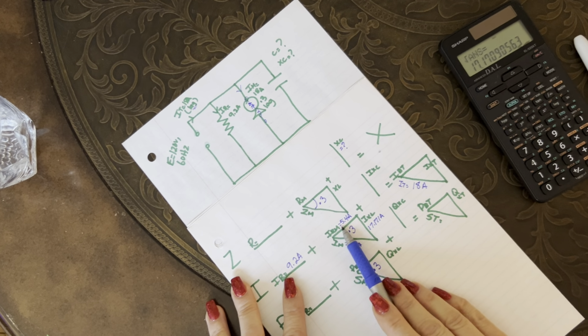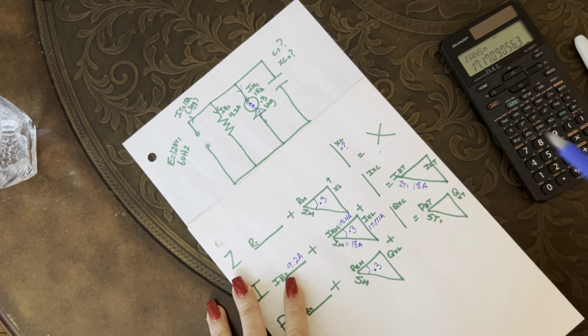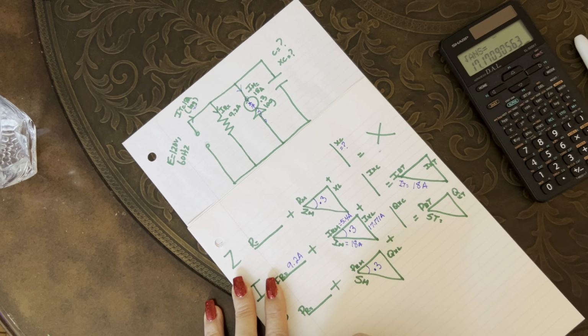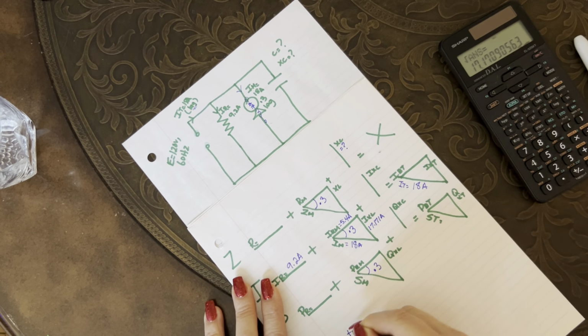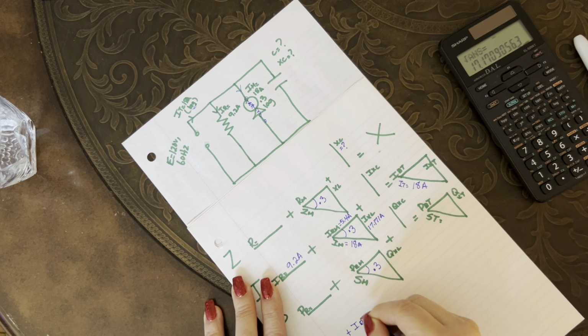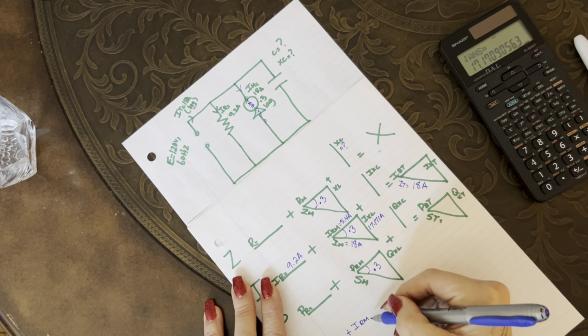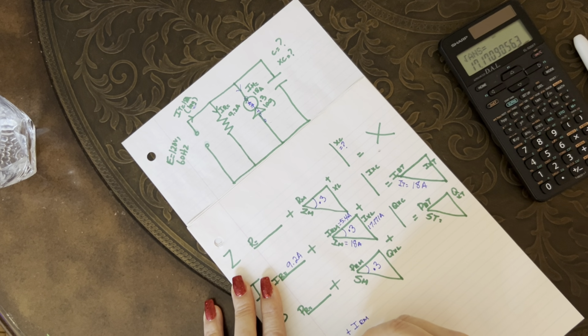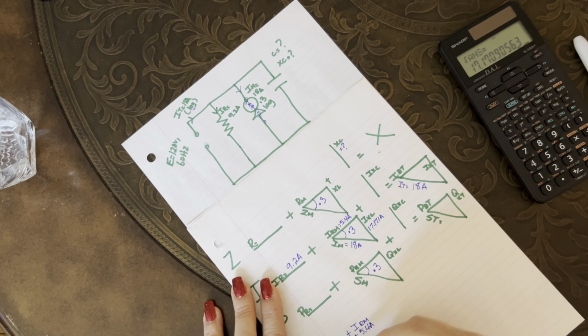So I can take those two values to populate my IR total for the circuit, right? So my IR total equals IR plus IR motor. The current flowing through the resistor is in phase with the current flowing through the resistive part of the motor. So that's 9.2 amps plus 5.4 amps for a total of